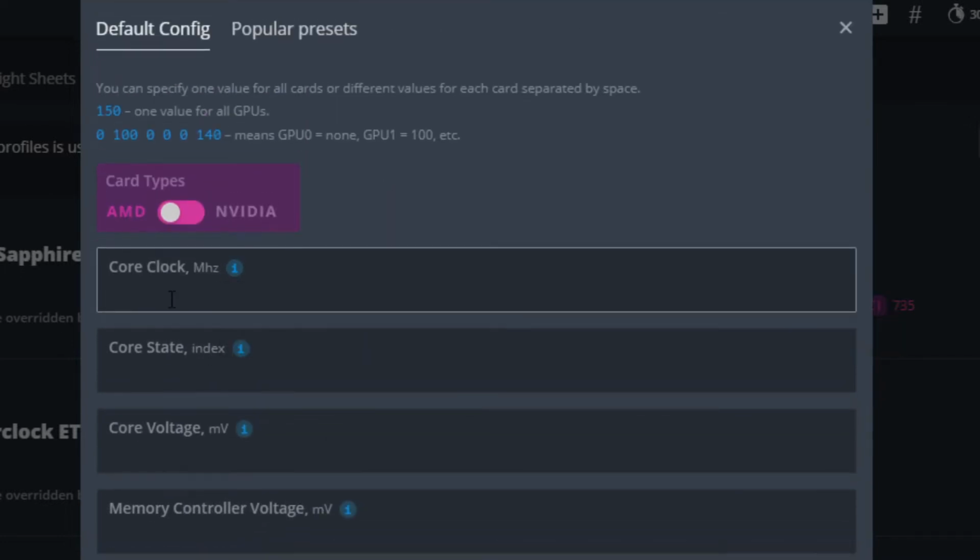For this particular example, we're looking at mining Ethereum Classic or Ethereum on the RX 570 or 580 video card. These overclocks will particularly be set for the RX 570 or 580. They will work for the 400 series of cards, but this is mainly for the 500. So for the core clock, I'm going to start with a very generic 1100, or maybe 1110 megahertz on the core.